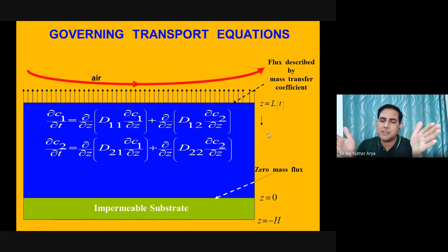So in that case, we are not expecting any shrinkage in the lateral side. We are considering only the vertical side. And these are the flux boundary conditions, how this mass transfer would change. We can provide hot air on top and bottom also. That depends on what type of object we have. If we have a movable one, we can provide hot air on top and bottom both.